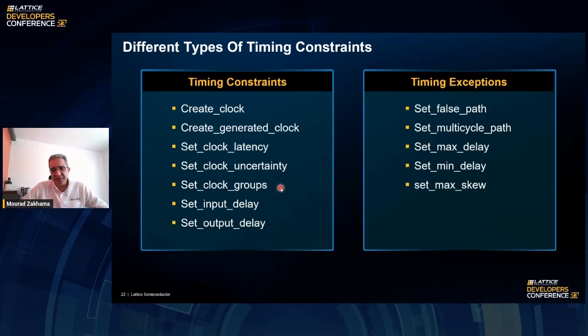Like in the dual clock domain situation and clock domain crossing timing analysis we've seen, if we put clock A and clock B in different groups, then the STA tool will automatically ignore any timing paths between the two. But you have to be careful when you do that, not to do it without knowing the consequences.